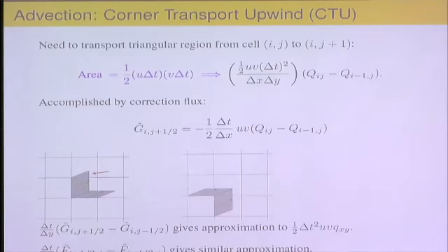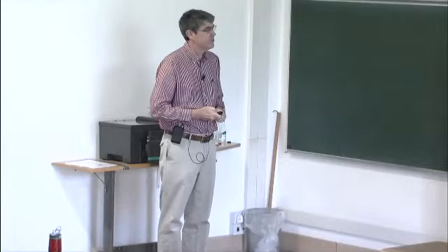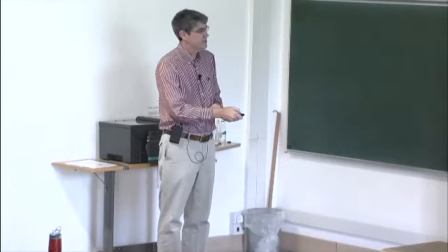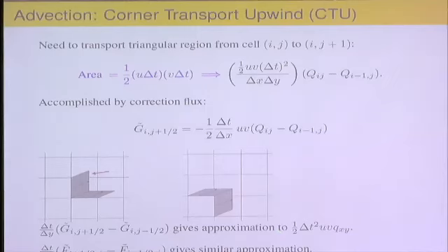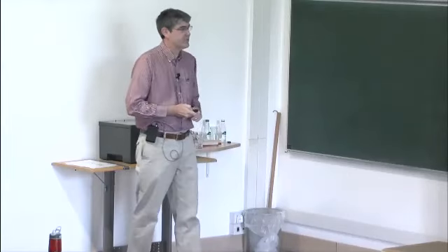But that's the flux at this top boundary. We do a similar thing here, and then both of those come into updating this point. And so in the end, what we get is like a y derivative when we difference this g tilde in the y direction of this x derivative times uv with a factor of 1/2, which is looking a lot like the term that we need in the Taylor series, which is shown on the next slide, I think, but it's basically approximating this cross-derivative term that comes into our second-order Taylor series expansion.